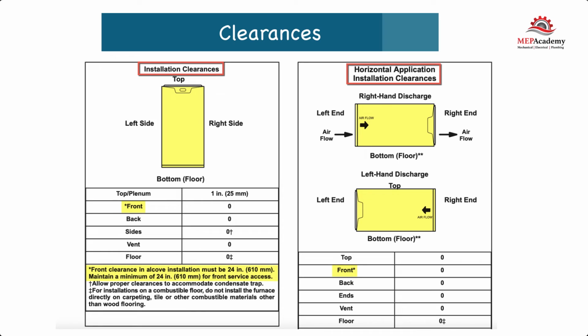Operation and maintenance clearance requirements. Check the furnace manufacturer's literature for the clearance requirements around the furnace. These clearances are for safety reasons, such as preventing a fire from occurring to the surrounding construction materials. Clearances are also established for proper access to internal components for maintenance personnel.